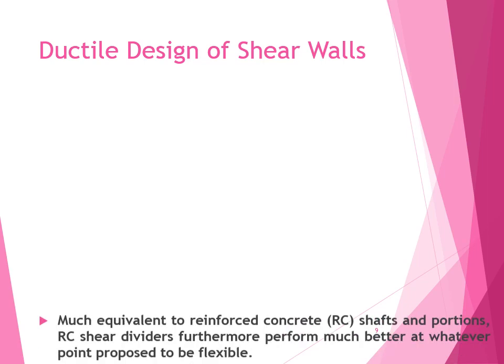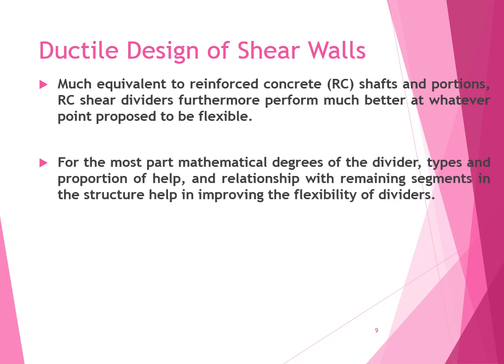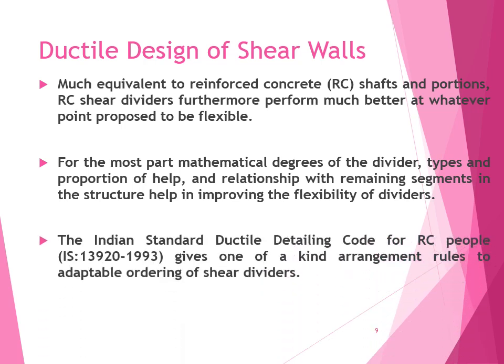Ductile design of the shear walls. Much like reinforced concrete beams and columns, RCC shear walls also perform much better when designed to be ductile. The overall geometry of the wall, type and amount of reinforcement, and the connection with the remaining members in the structure help in improving ductility of the walls.